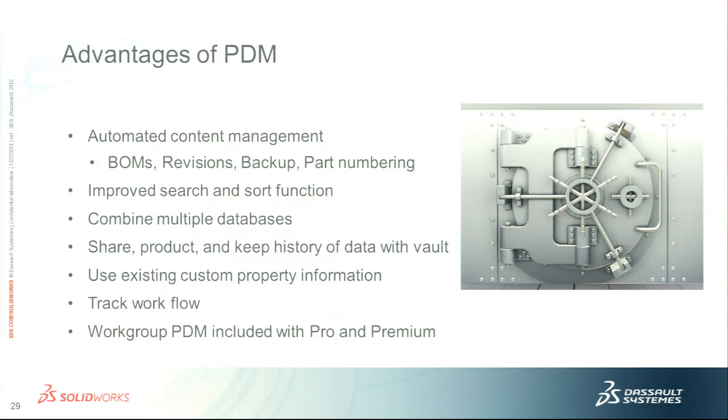All right, so we got through the hard parts, the ways that I had to get by with file management. Now we're going to talk about the advantages of using a PDM software. A lot of this stuff is going to be automated for you, so you don't have to be concerned with your bills of materials, your revisions, your backup, your part numbering. PDM is going to handle that for you. There's improved search and sort functionality. You can combine multiple databases with the PDM software.